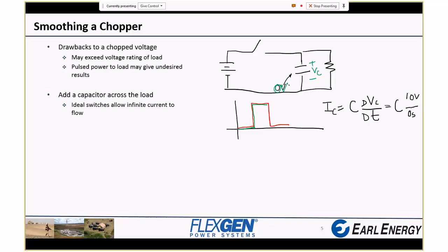Divide any number by 0, and you will find that IC approaches infinity. So all you've done by adding the capacitor is cause these infinite pulses of current, which I'll draw on an imaginary second set of axes here, right at the switching instant going into the capacitor, forcing its voltage up and down.